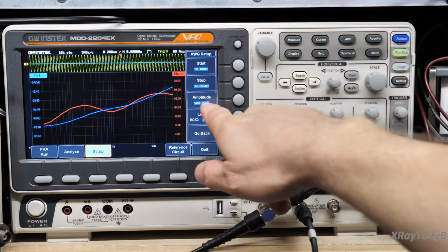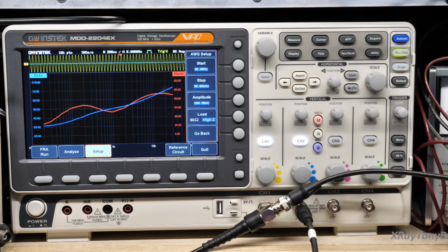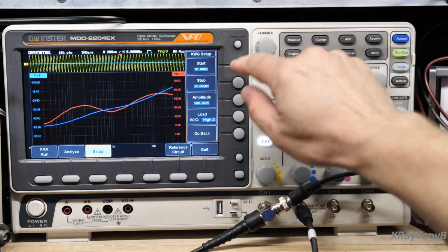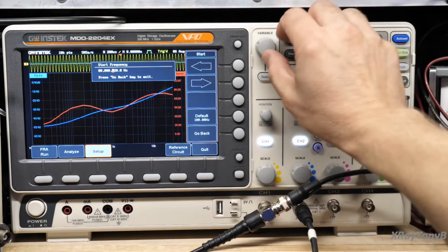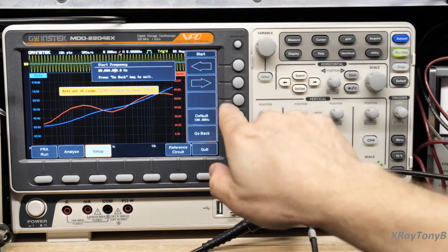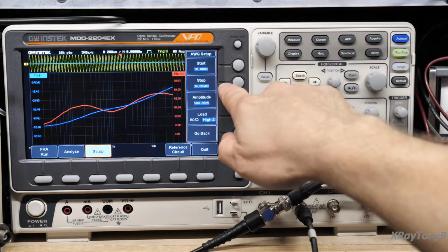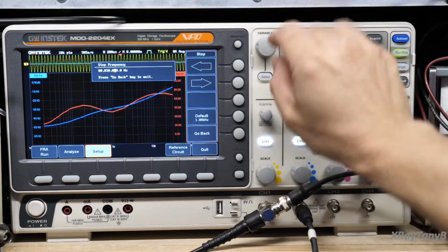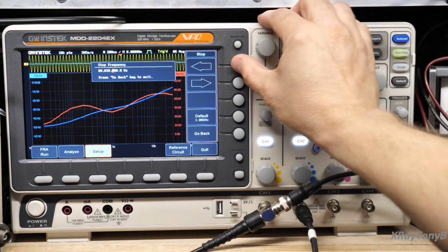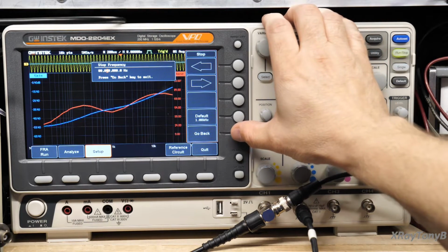So anyway, this represents a line level signal. I'm just going to set it to about 500 millivolts. Some are higher than that, some are lower, but that's a pretty good spot. And again, we're going to measure from, it can only go down to 20. I'm sorry, I kept saying 10 hertz. This only goes down to 20 hertz, and it's stopping at 30 kilohertz. We can even run that up to 40 kilohertz if we like. So that's double our hearing range, right?